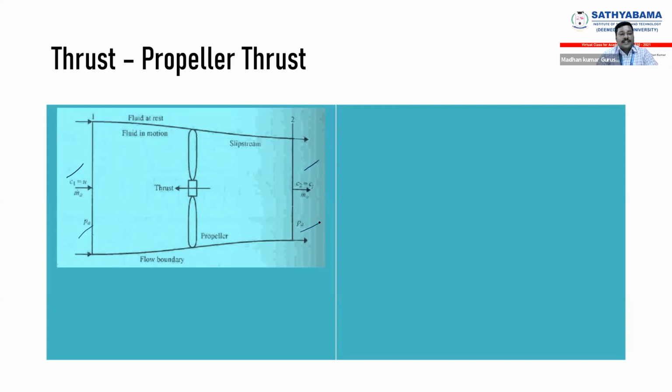So in this propeller engine, I am going to solve the first equation, the momentum equation, right? So what is your momentum equation? Force F is equal to ma, mass into acceleration. But here we are considering the mass flow rate, so you multiply the mass flow rate with velocity, right? Mass flow rate with velocity, that is momentum. So mass flow rate of air with respect to velocity: m dot a into C2, that is exit, minus m dot a into C1.